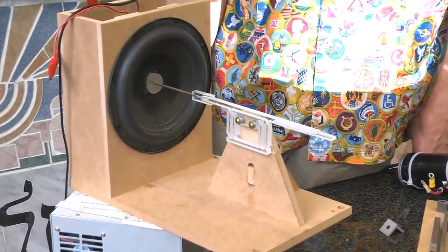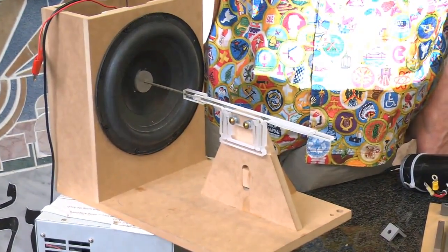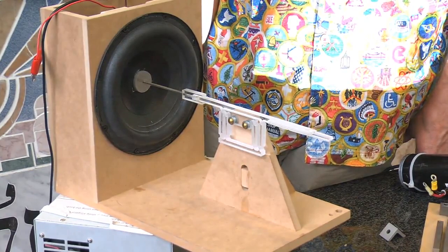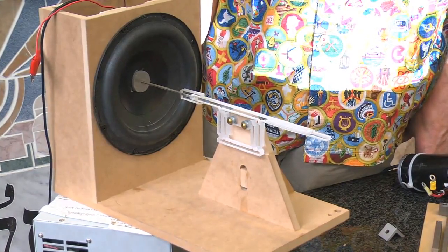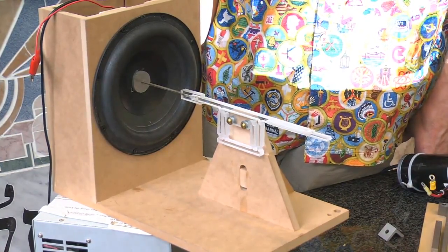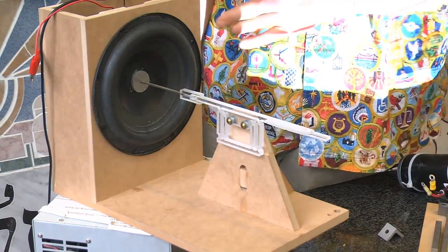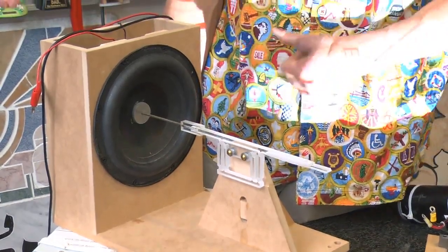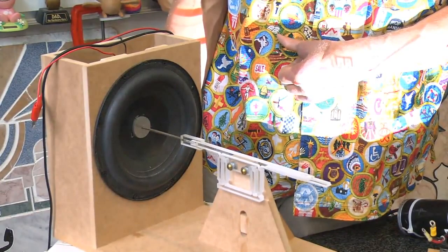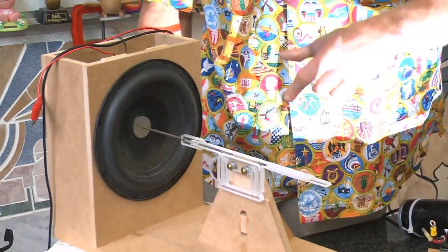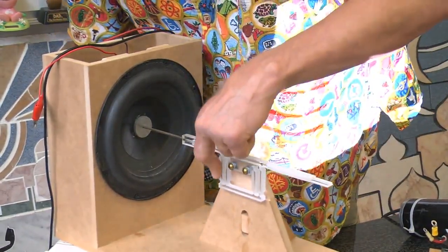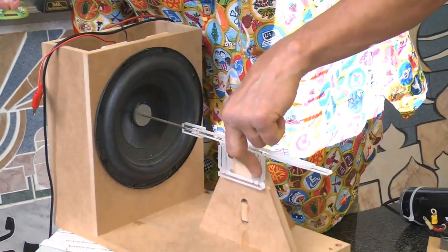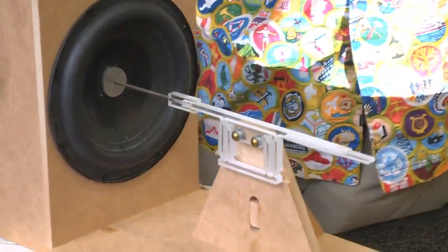Now this is very low frequency, so only the whales out in the ocean here are starting to dance to this. But imagine, I can use this Lorentz force actuator, which is what drives the speaker, as an actual actuator to drive this system. And notice, by the way, how we're using one of these folded flexures we talked about earlier in the linkage